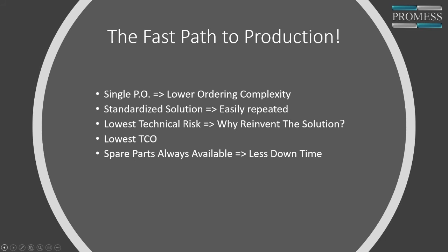can your kit calculate what size shims I need to put in? That's a good question. In a lot of backlash applications, you're testing the backlash to determine whether the fit is correct in the gear mesh already or whether it needs to be adjusted. Typically in some assemblies, shims can be entered to do that.